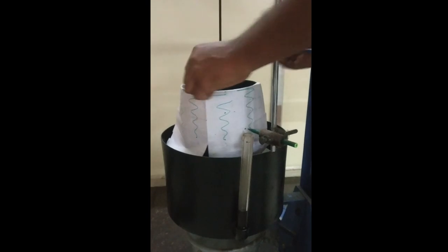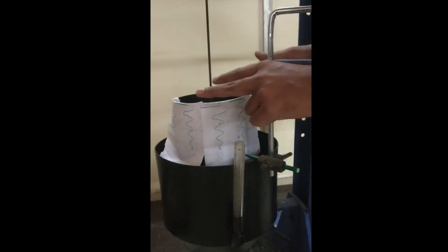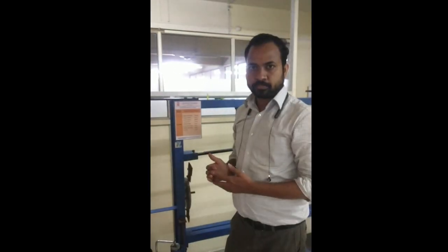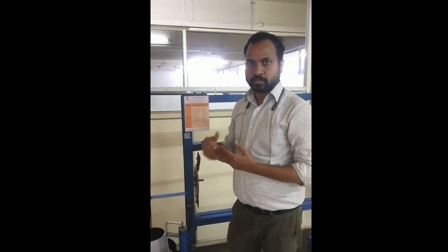Now in the second case the same experimental procedure is there. We drain the oil from this drain and repeat the procedure. Again I provide torsional vibration, again this pen is at the top position, it will move in a downward direction with constant velocity, and again it will plot a graph. So we will get two plots. For each case we are going to record 3 iterations, and out of these we will get 3 graphs and measure the respective amplitudes; its calculation can be shown to you in the calculation part.